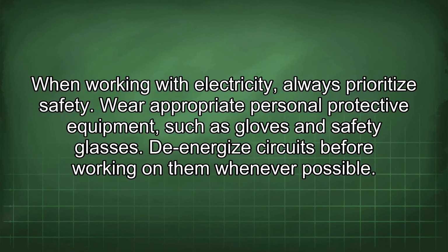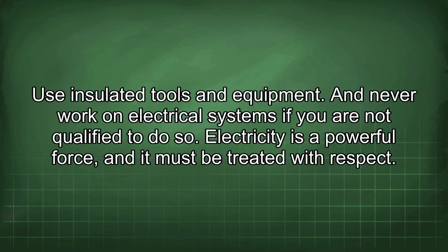When working with electricity, always prioritize safety. Wear appropriate personal protective equipment, such as gloves and safety glasses. De-energize circuits before working on them whenever possible. Use insulated tools and equipment. And never work on electrical systems if you are not qualified to do so.